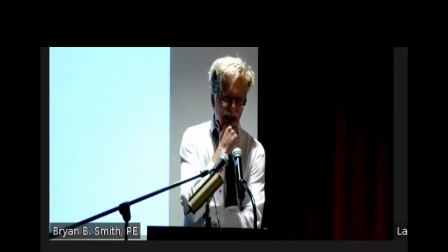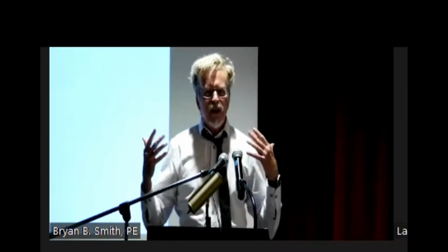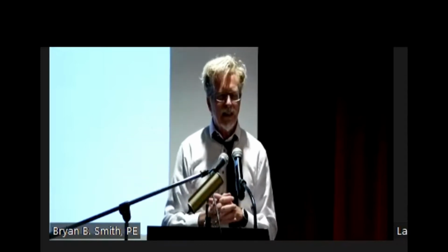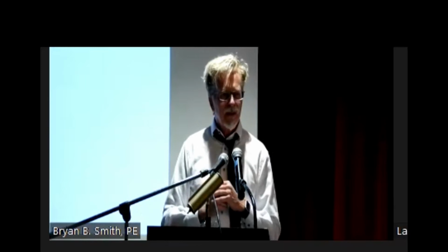It's like 4,000 feet per second, and I'm recording it once a second. I'm not recording anything. So you have worthless data from your pressure transient. You have this negative wave going down the piping system. And then what happens? Negative wave. Sorry, cameraman, we're following the wave. I'm going 4,000 feet per second.